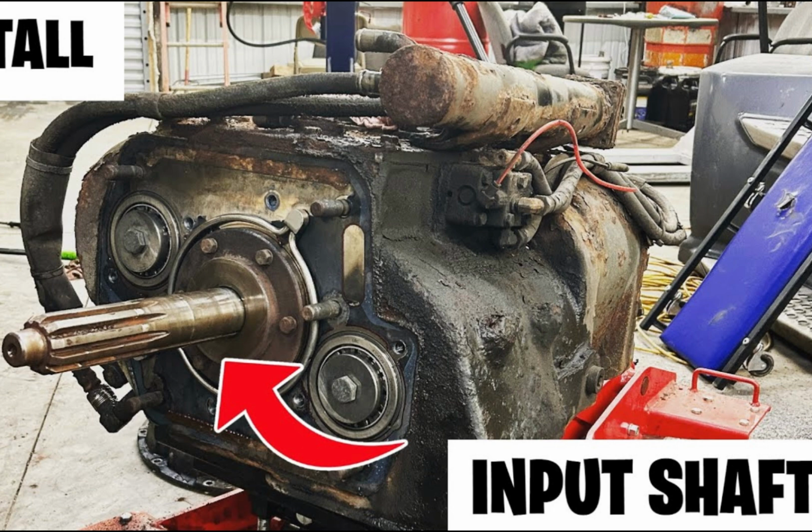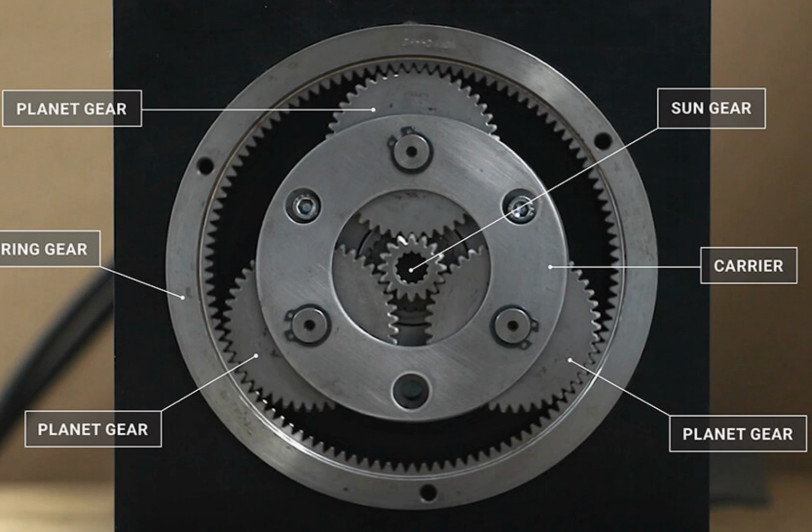Driving and gear shifting. Power transmission. The input shaft receives torque from the engine and passes it to the planetary gear system. The planetary gears adjust the torque and speed depending on the selected gear ratio. The adjusted power is sent through the output shaft to the drive shaft, which rotates the wheels.